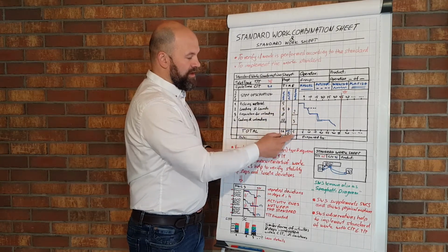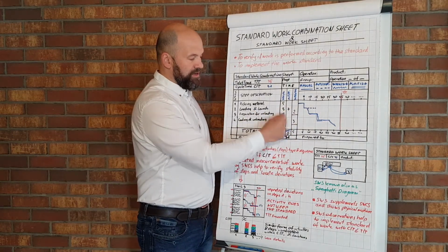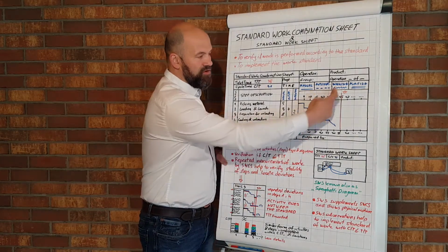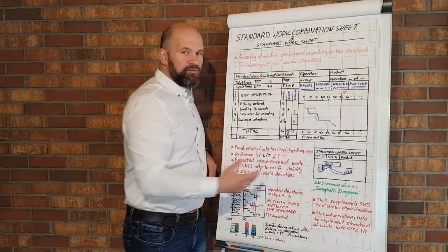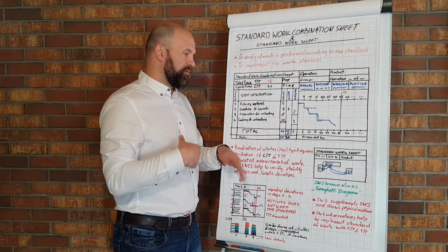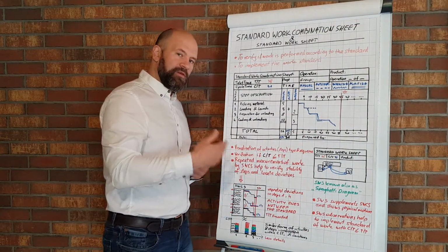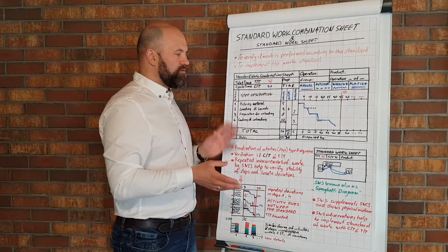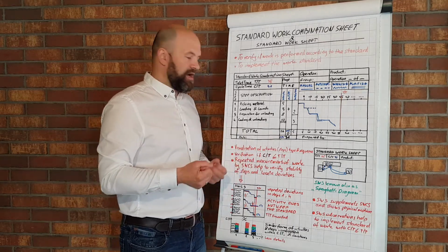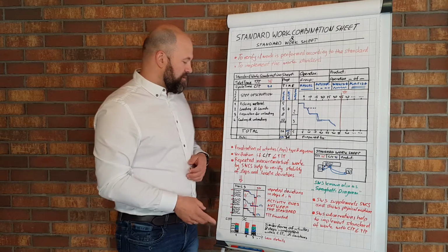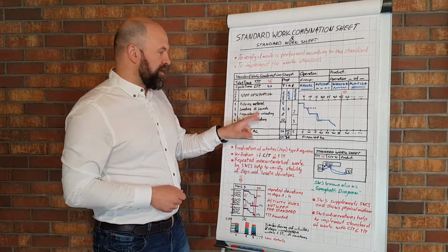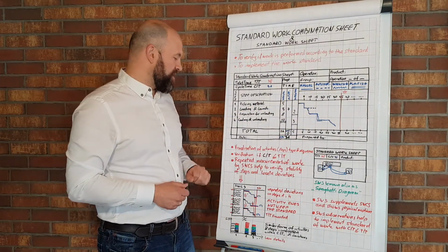And at the end you make a summary of the time calculated, measured, and you check your cycle time and compare it with the takt time to check if you match the takt time defined by the client. If you exceed it, it means that you will not finish on time unless you implement some remedial actions in your processes. So these tools help you to visualize activities, the steps, the types, and the duration.